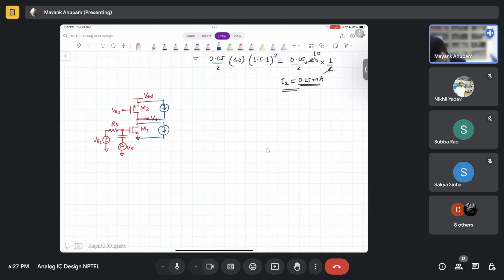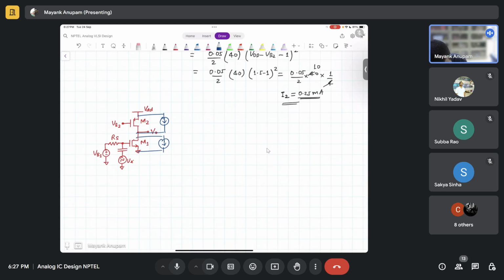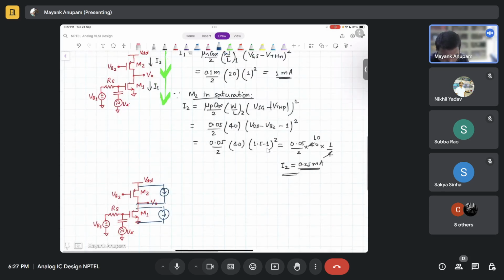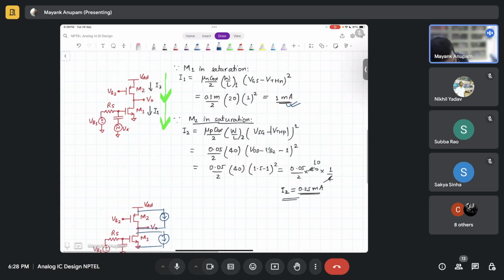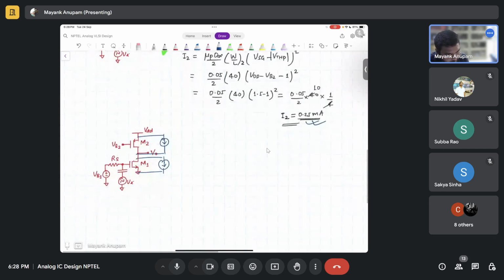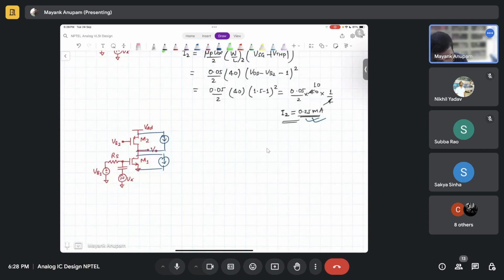Yes. So now tell me, if these are basically two current sources competing with each other, right? As one of you rightly pointed out, the current should have been the same here, right? 1 milliampere and 0.25, they are different currents. So what happens if their currents are different? The final one will prevail, I think. So this is 0.25 milliampere. So this is 1 milliampere.